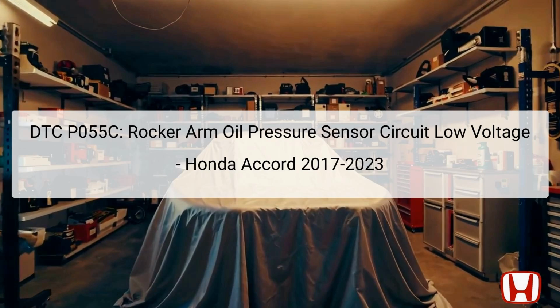The DTC P055C indicates a low voltage issue in the rocker arm oil pressure sensor circuit, specifically relating to the sensor's ability to send accurate readings to the powertrain control module, PCM. The rocker arm oil pressure sensor is critical for managing the oil pressure within the rocker arm assembly, which impacts